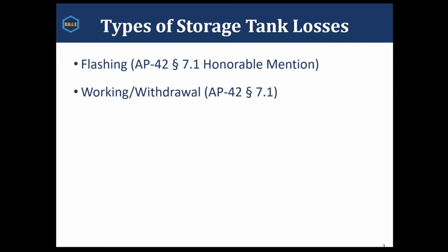We also have withdrawal losses. These are for floating roof tanks. As liquid is pumped out of our floating roof tank, some amount of liquid clings to the sides or the fittings of that vessel and evaporates, and that's what we call withdrawal losses.